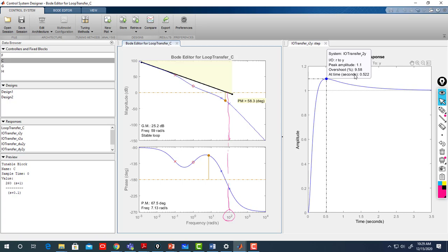Also, if you want to keep it at where it was, somewhere not here of course, but whatever it was, it gave me around 12 overshoot, which is considered as acceptable. So you can follow the same analysis. But again, I don't recommend you to do the design requirement. Just for verification, we can be sure that it's 20 decibel per decade and crossing over here with the KV value. Good. That's it for exercise 2 and 1.